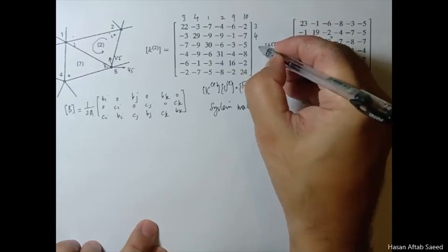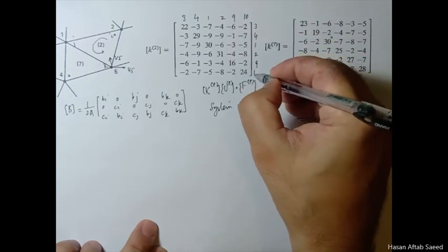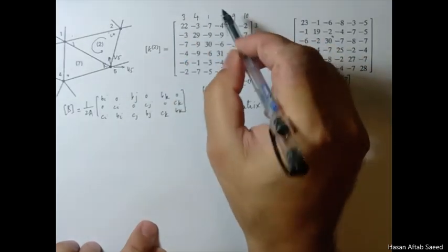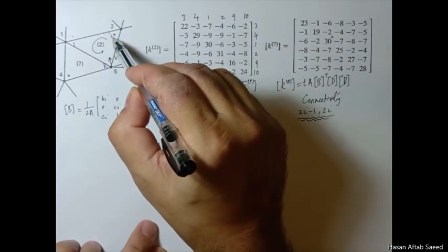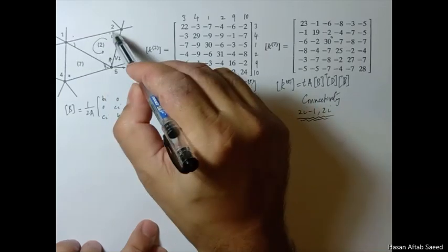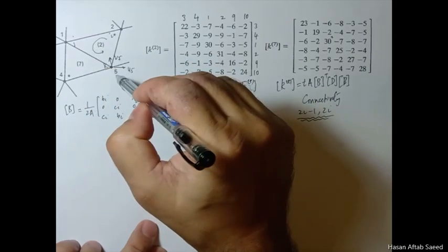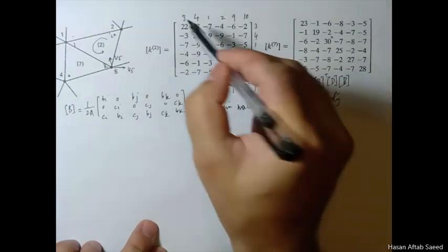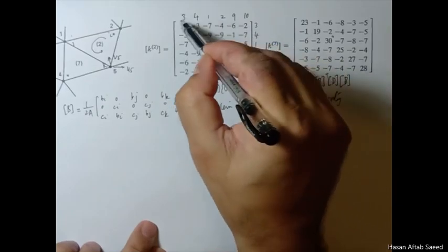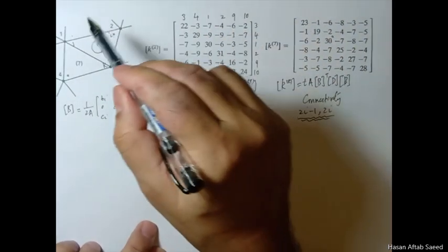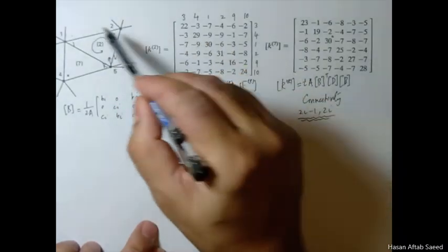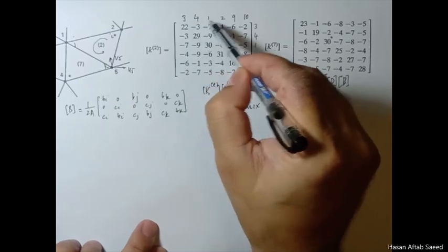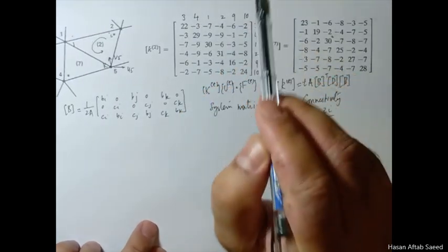Similarly, the same sequence has to be here. There should be no difficulty about this, because once you specify that the I node is this one, then for the rest, number 2 is I, then J is 1 and K is 5, because you always follow this convention of counterclockwise. So these numbers must be in this sequence. The moment you mesh them in this kind of a scheme, the values you get depend on this scheme. So if you change the sequence here, there'll be a problem.